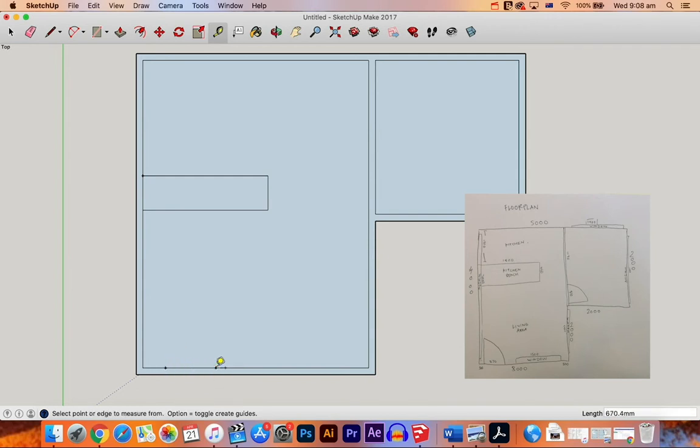So there we go. We're going to put another one to show where the door is, and that's 870 millimeters wide. We can then see from this side, there's a point where the window is, and that's also 300 millimeters. And then, that's not right. We're going to put where the window ends, so that is 1,500. And that's a bit too long. So in my drawing, I've been a bit adventurous by choosing a line that's that long. So here we're just going to make it 1,100.